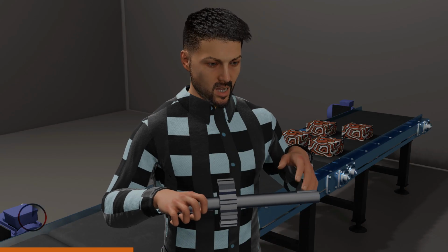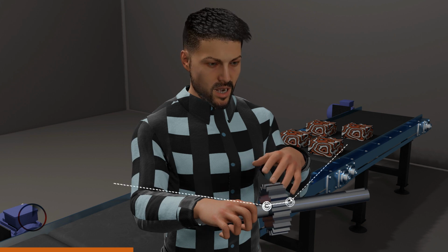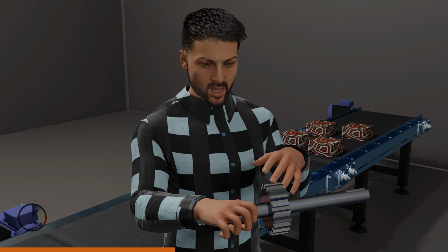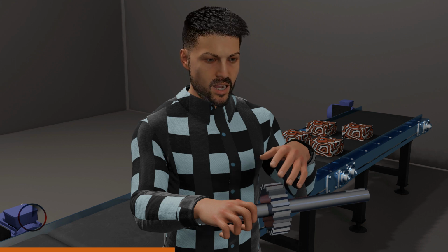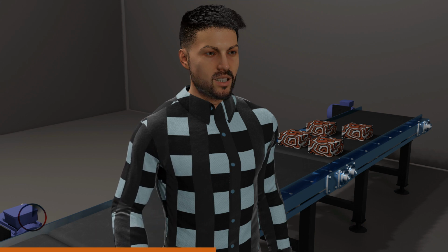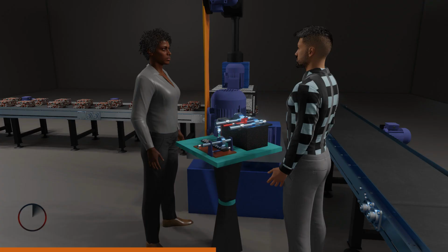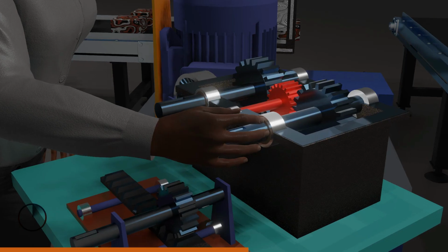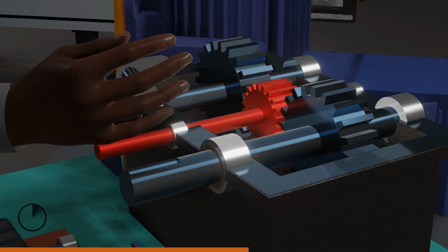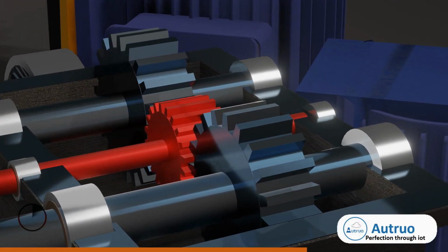Spur gear comes in the form of a cylindrically shaped gear, and the teeth are straight and parallel to the axis of rotation. With this teeth design there comes some ease during the gear design. This means the gear can easily be fabricated with the right tools when available. Spur gears, or straight-cut gears, are the simplest types of gear. This is due to the arrangement and the design of the gear teeth. These gears consist of a cylinder or disc with teeth projecting radially.